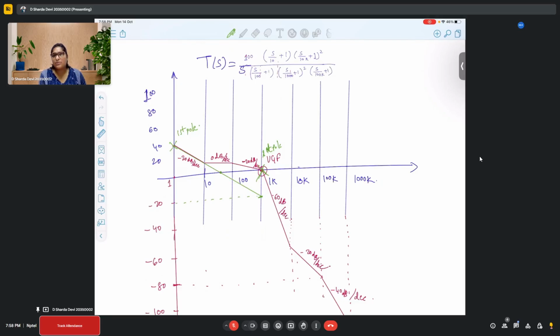Yeah, because it's like you'd be drawing your graph, right? When you're drawing your graph, you would place your first unit as a decade apart. Always one unit is a decade apart, and then all others follow. So it's 1 decade apart, always. So if the first pole or zero is appearing at, let's say, 10, you can start with 1. If it is appearing at 1, you can start with 0.1. If it is appearing at 0.1, you can start it at 0.01. So maybe 1 decade ahead.